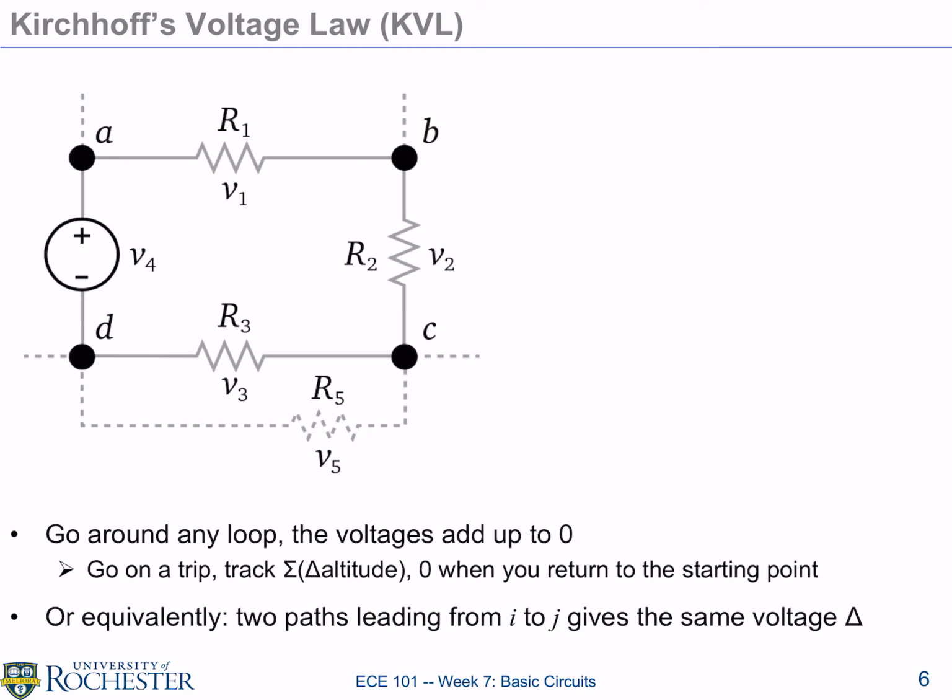Okay, so KVL. What is KVL? We know what a voltage means, or if we don't, we're familiar with it now. We measure it. It's a fundamental property of the circuit. At any element, at any 2 points in the circuit, there's a potential difference, a voltage. This is sort of like temperature that you are familiar with. In the room, there could be lots of difference in absolute temperature, so there is temperature difference. So the voltage that we're talking about is usually the voltage difference or the potential difference.